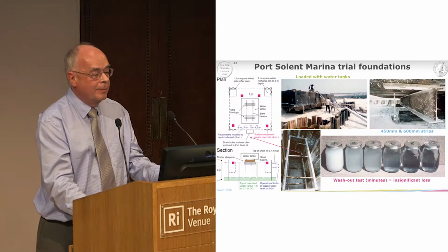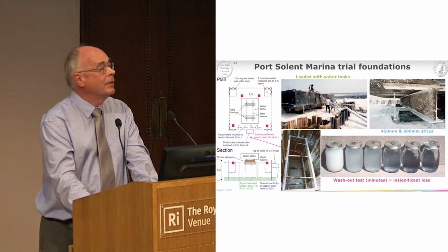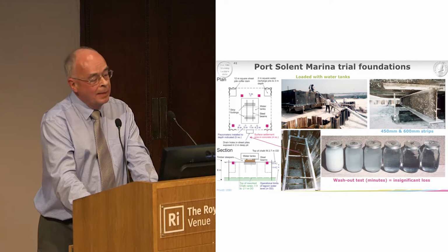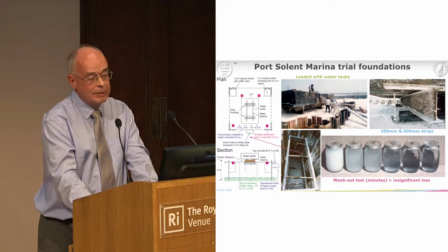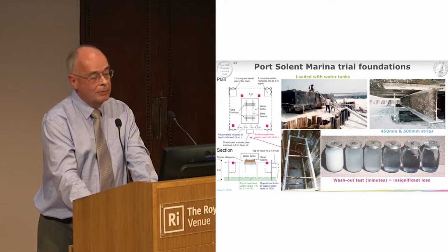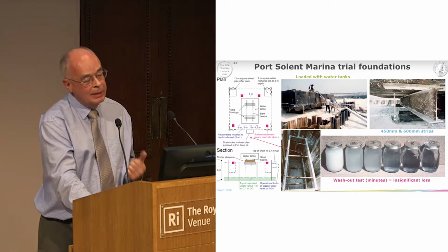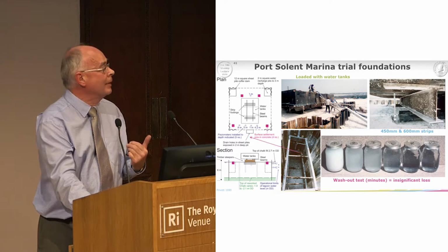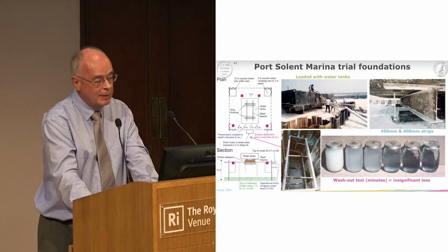And this is the trial foundation test. We produced 2 different sizes of foundation and loaded them with water tanks, and then measured the settlement with precise levelling techniques. This is the first test, and you can see it's surrounded by a sheet pile cofferdam. We dug a couple of holes in the corner. We could put water in, pump the water out to simulate the tide going up and down that was measured with a series of piezometers.